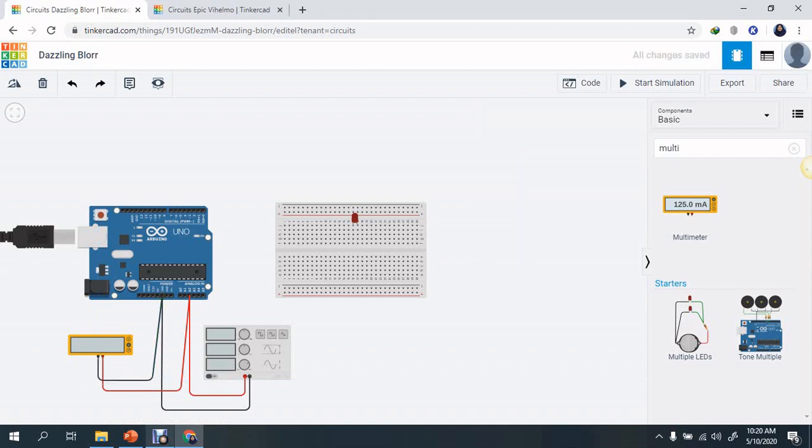And then you take one digital output, any port, to light up this LED. For example, in this case, I am going to use a PWM pin, because we are going to use the value that we receive from the function generator, and then we are going to write the analog value onto that digital port by using the PWM function.